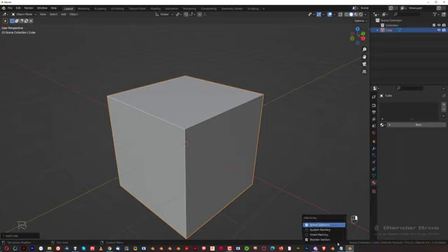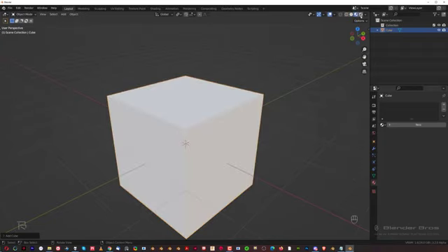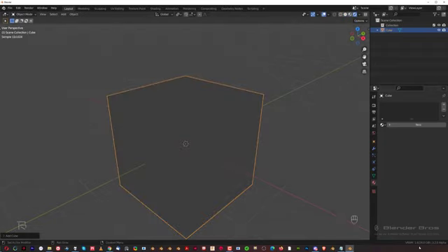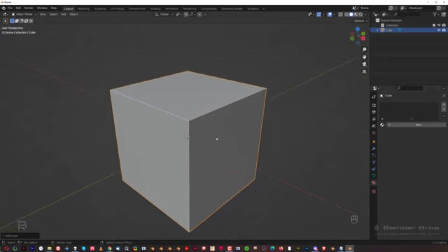Okay. Now you can turn it off, and you can, for example, turn on video memory. So if you turn on video memory, you will see how much of your video card memory you are currently using, okay? And if you switch to stuff like look depth or, for example, render view, this video memory is going to go up depending on what you have in your scene, okay? So that's an interesting menu to know. And this will be it, guys, for the time being. I think that's enough to know for starters.